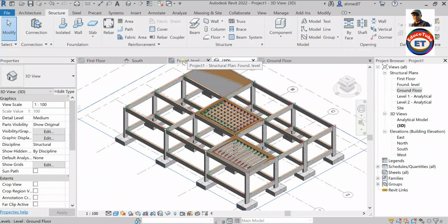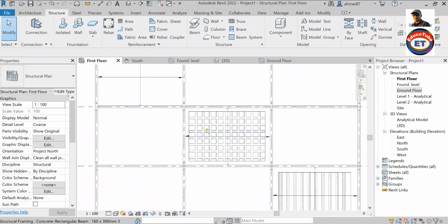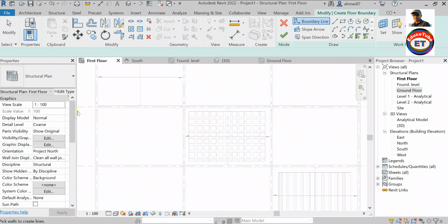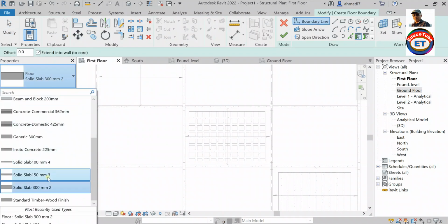Now, one important point is, say this is the ribs. In between the ribs, there is an empty place, but I need a topping of 10 centimeter. All hot slab at the top, there is 10 or 12 centimeter topping slab. So that slab I want to provide here. So what I will do, I will go for the slab, and here I will select that 10 centimeter.